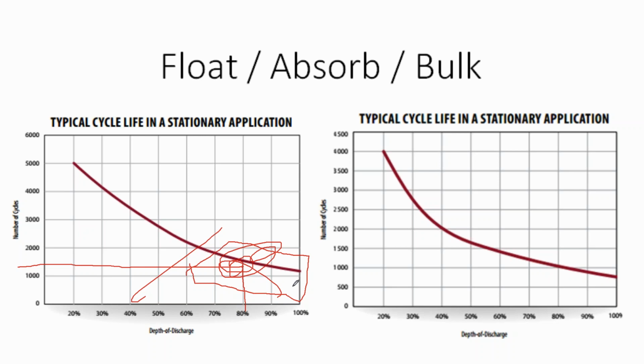Your battery manufacturer will say, no, you can discharge them a few times. You can discharge it 1,000 times and it'll charge back up again. It just won't do that 5,000 times. And so it's not generally cost effective to operate the battery down in the bottom of this range.